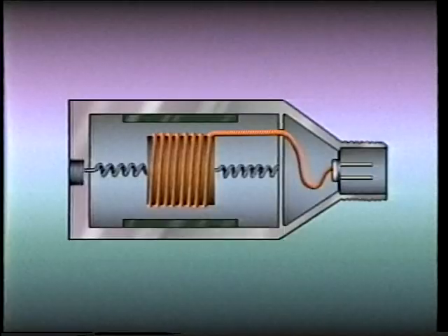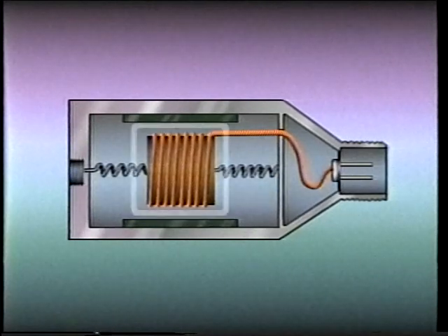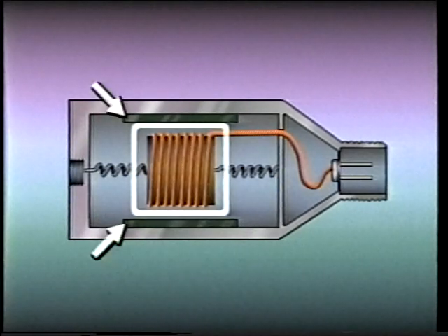The contact pickup, which is also known as a transducer, is attached directly onto the component that is to be monitored. Once the transducer is in place, it can detect the amount of displacement, velocity, and acceleration that the component is experiencing. There are several different types of contact pickups available. Two of the most common types are velocity pickups and accelerometers. Velocity pickups consist of a fine coil of wire surrounded by a magnet.